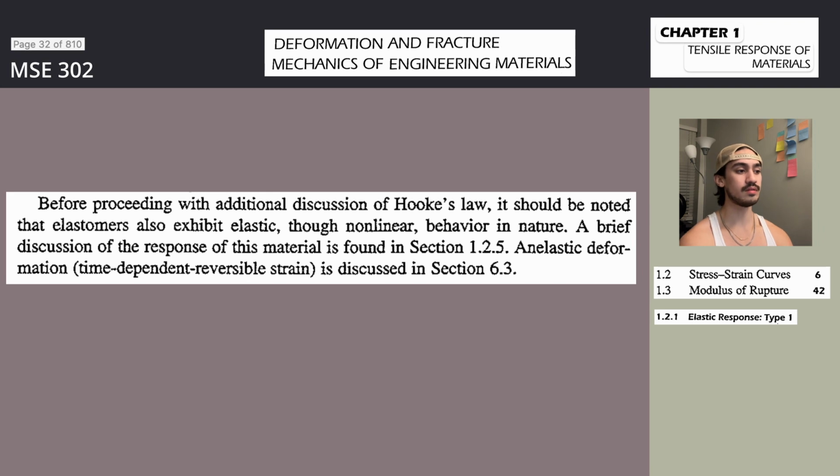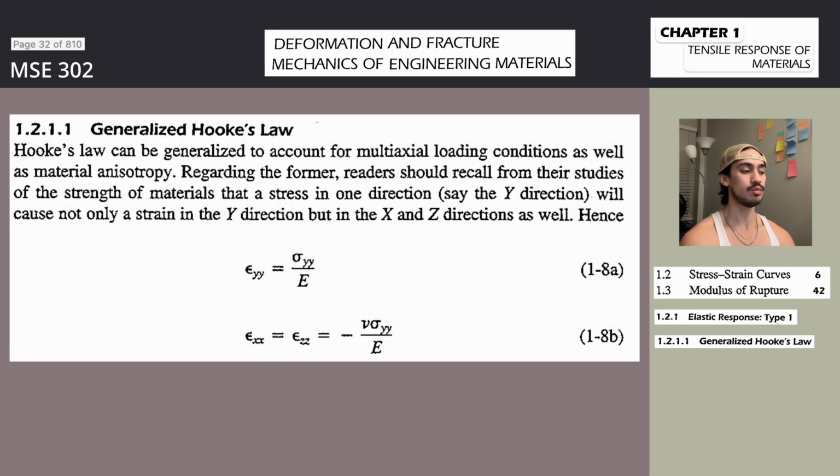Here we see the same elastic region at small strains, but now we find a smooth parabolic portion of the curve, which is associated with homogeneous plastic deformation processes, such as the irreversible movement of dislocations in metals, ceramics, and crystalline polymers, and a number of possible deformation mechanisms in amorphous polymers. That the curve continues to rise to a maximum stress level reflects the increasing resistance on the part of the material to further plastic deformation, a process known as strain hardening.